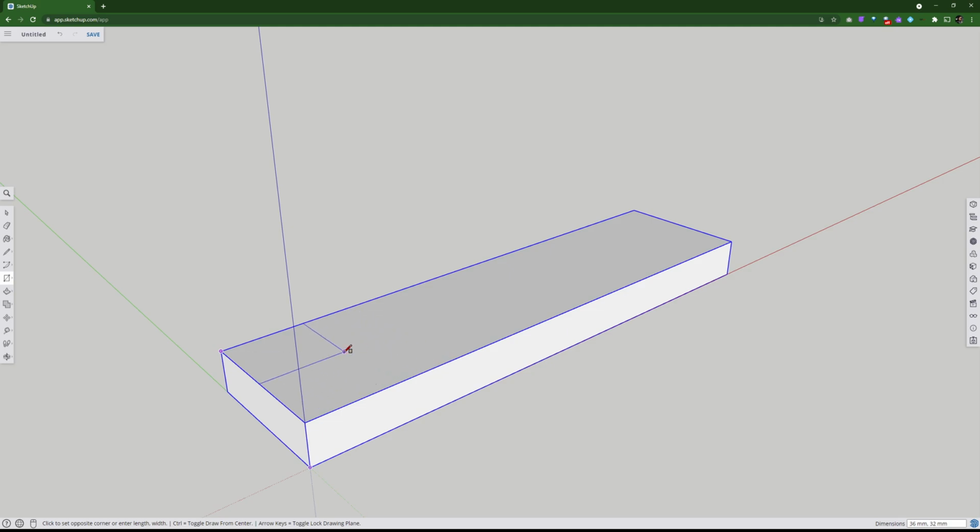Now, I usually move my mouse so I can get a bit of an idea of the orientation I'm going. See that down the bottom? It goes 100, 85 or 65. Okay, so I'm just going to type in. Now, I don't have to click in that box. I didn't mention that before. I just type what I want. 65, comma, 65, no spaces, no full stops or anything like that. If I did a full stop, it'll be like 65.65. So 65, comma, 65, hit enter.